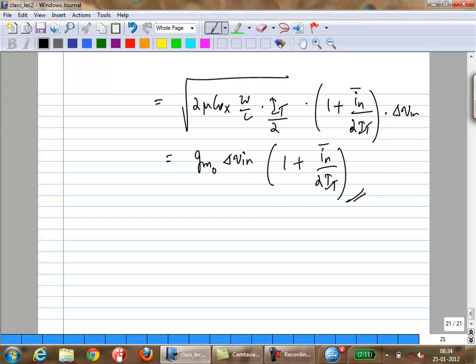So what is this? This is actually a differential noise at the output, because it's delta ID1 minus delta ID2 multiplied by RD, right? You'll get a differential noise at the output. But you also note that it's actually multiplied by delta Vn for small perturbations. Typically, if your Vn is quite small, right? If you're considering small signal, it's not a very prominent effect. Okay? Normally, the current source noise is suppressed to a large extent. Okay?